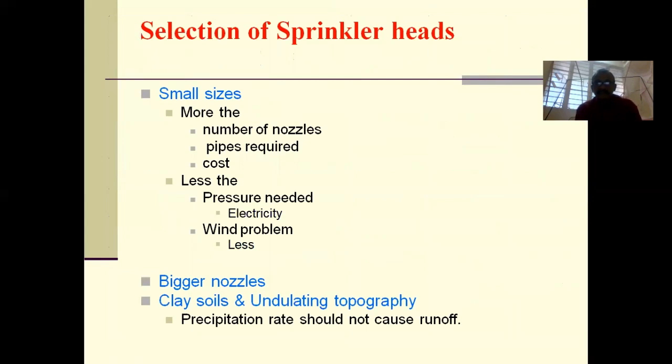So one has to decide whether to go for small size sprinklers or for bigger size sprinklers, depending on one's preference. If one wants to invest lower cost, one can go for larger sprinklers, and uniformity will get decreased. So accordingly, one can select whether smaller sprinklers or bigger sprinklers.